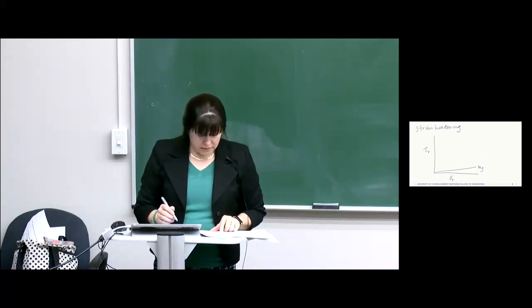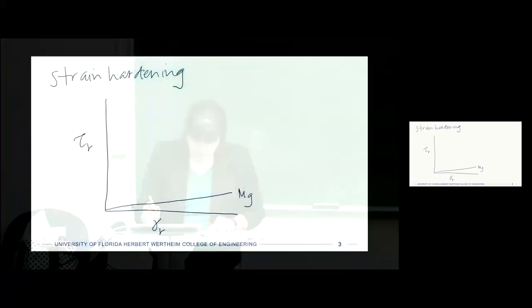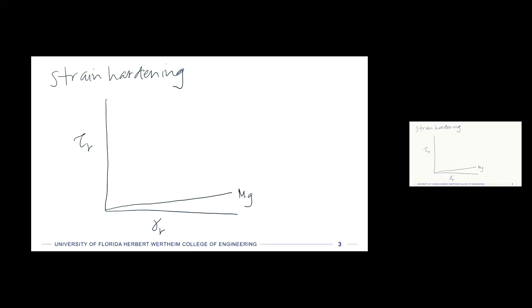And we can have another one which has kind of a fun behavior, which is copper. If you've ever played with copper or done an experiment with copper, you know that it's very ductile, and so that also comes into play in its strain hardening behavior. So I'm going to draw a curve with a couple of different inflection points like that. And so you can divide it up into different regions, right?